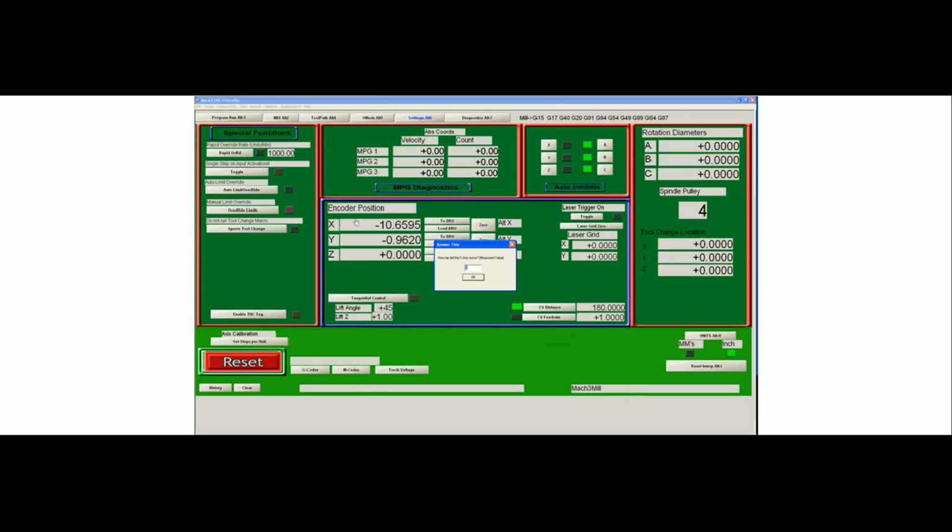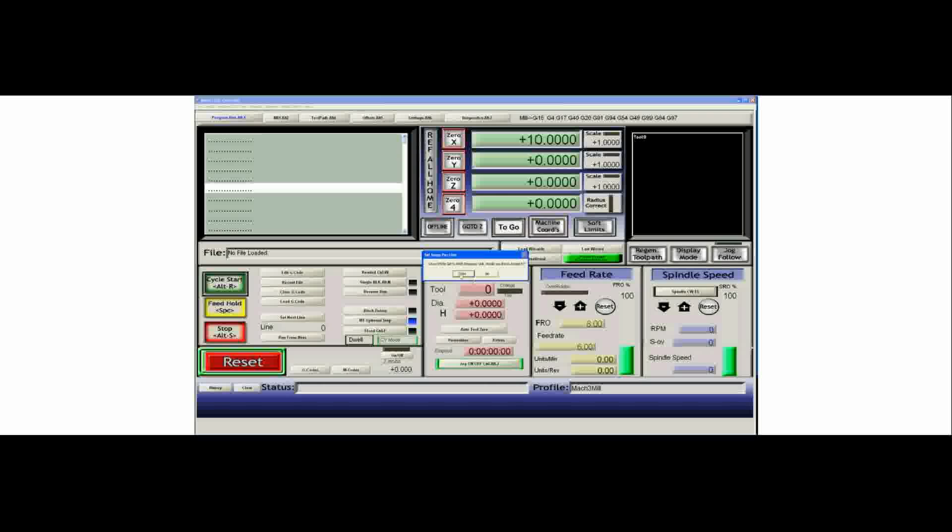When we do that, the system actually moves. If we now measure the system, your axis would have just moved from its position to a new position. You have to measure that movement. If we tell it that we actually moved 5 millimeters, it will now set the axis to 4,000 steps per unit, which will be accurate. We say yes, and the X axis has now been calibrated.